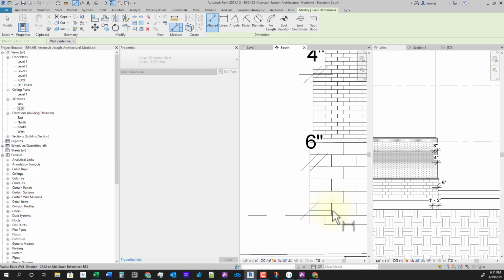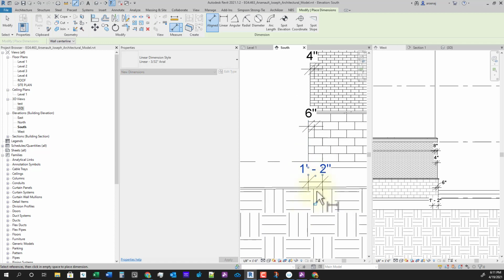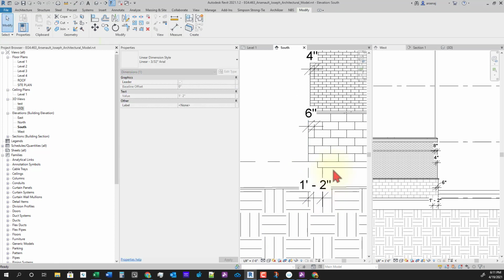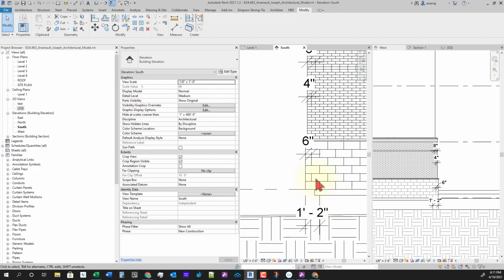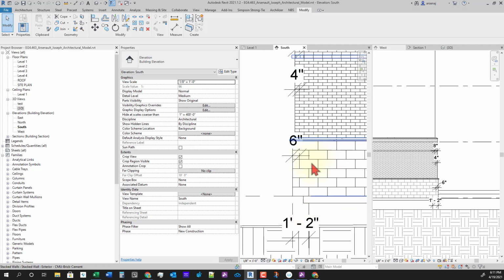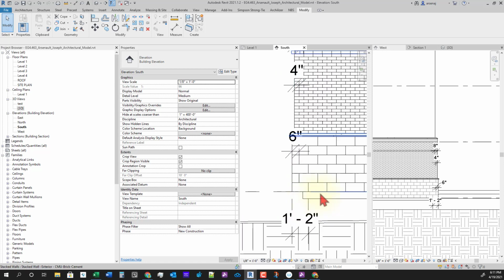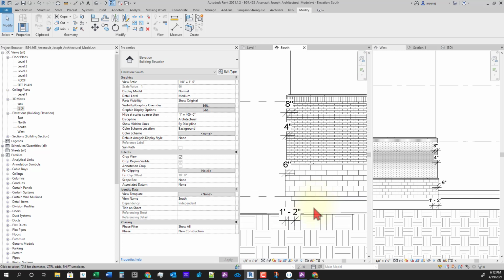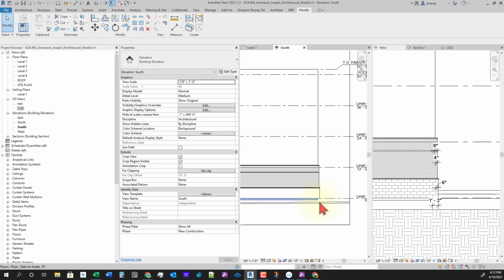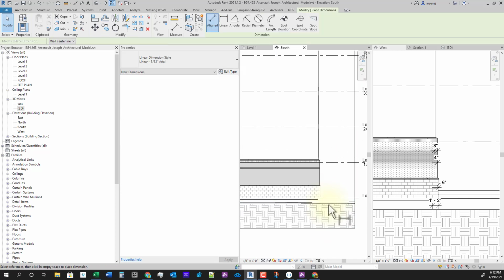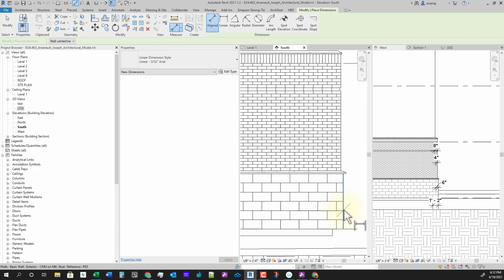Now I think the better way, so we're using a 8-inch tall by 16-inch wide by 6-inch deep masonry. If you were to use the 8-inch block, then this might work better because they would be in the same 4-inch dimension, which might actually be the best way to go. But for now, we're just going to line these up just so that you can fix them and we can get an overall dimension that we like, and we could change it later.